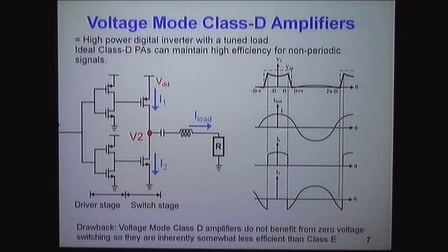What's nice about it is you can see that that can apply to a lot of different waveforms that you can imagine, so it's relatively simple to come up with ways you think you could make these two transistors switch to produce the sine wave, which is really dependent upon this resonant network here.